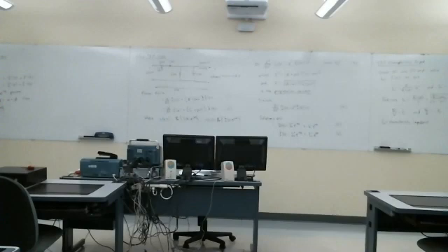Well, that's going to become minus alpha z plus minus j beta z. So that gives me e^(-αz). And then I'm going to combine all these terms that are multiplied by j. I'll have ωt minus βz, and then plus psi, the angle of this complex constant.